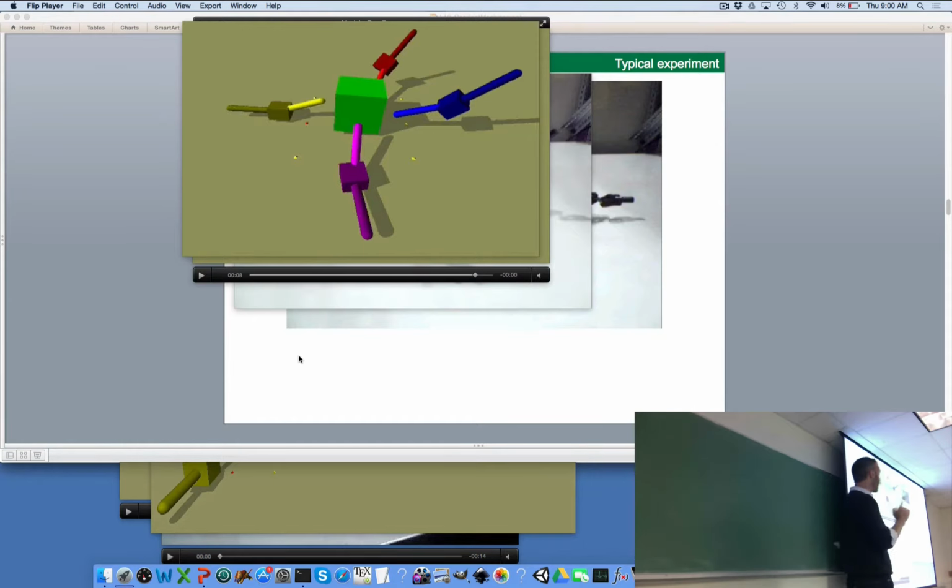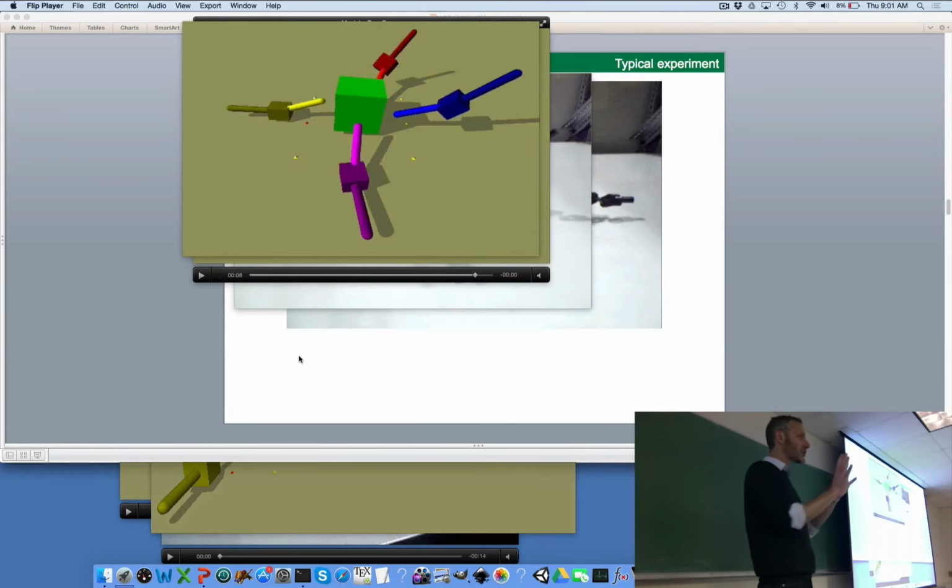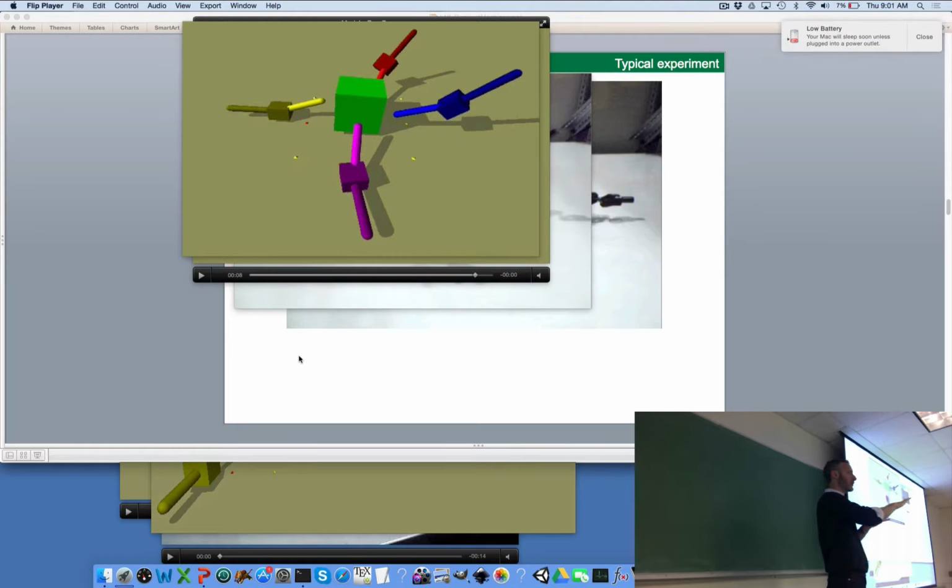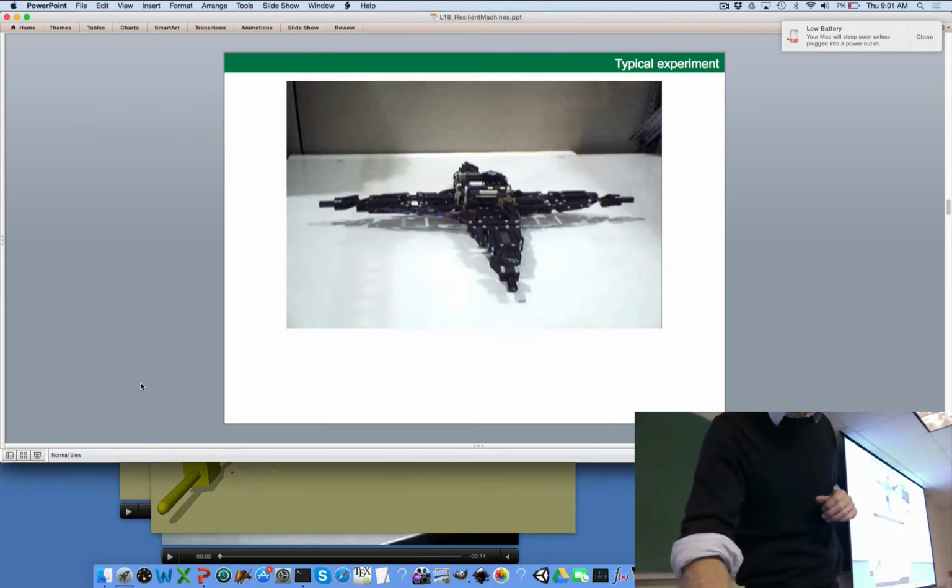So this is a really important point, right? Again, we're never going to have a perfect simulation. We want to have a simulation that's just good enough for us to transfer controllers from simulation to reality. How good is good enough, right? Here we have a system where it's able to try and improve that simulation. Even if some aspects are not under evolutionary control, like mass distribution or friction, it might be able to use the other aspects of the simulation that we put under evolutionary control, in this case geometry, to compensate for those things. Okay, so that's the first evolutionary algorithm, which is evolving a simulation of the robot itself.